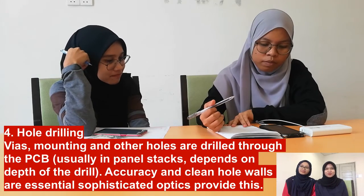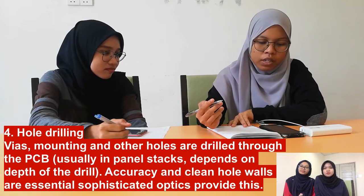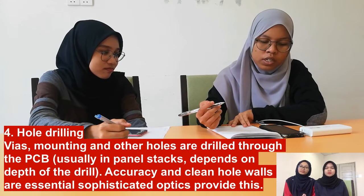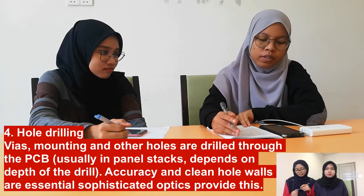The next step is hole drilling. Vias, mounting and other holes are drilled through the PCB, usually in a panel stack depending on the depth of the drill. Accuracy and clean hole walls are essential.